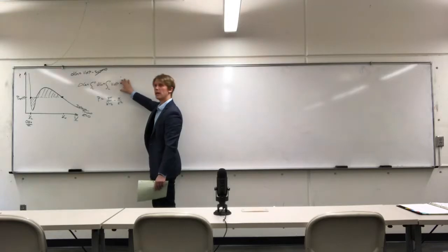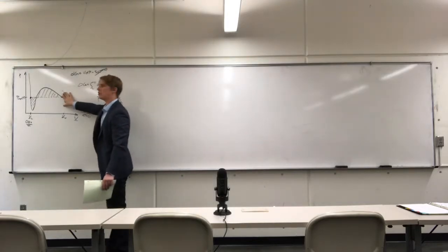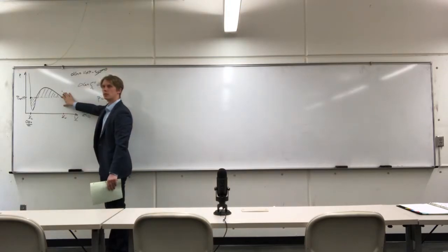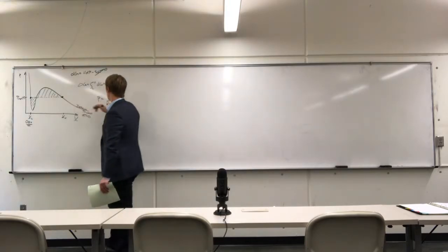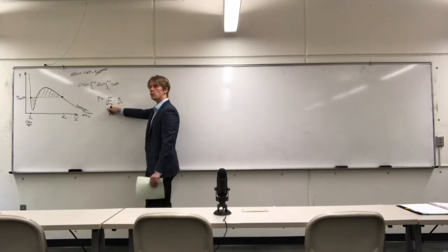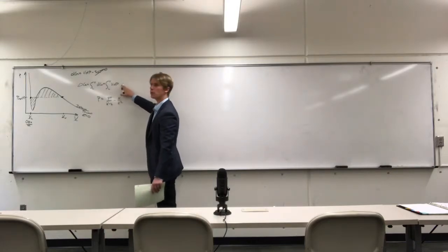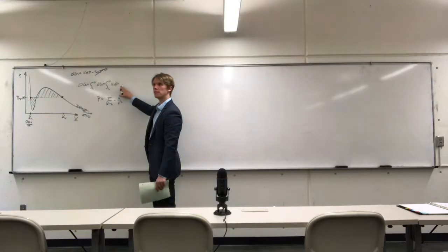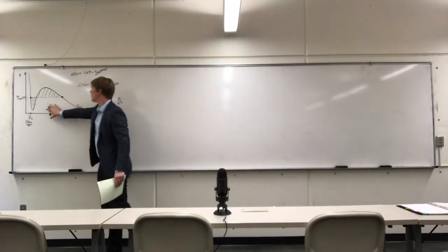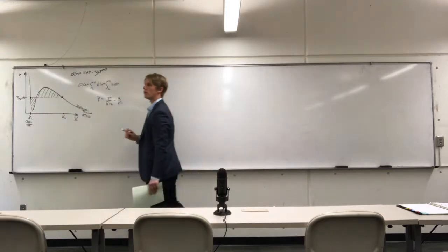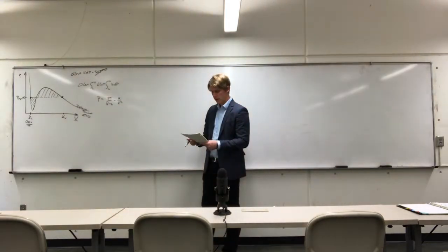If we wanted to apply this numerically, we would more or less have to discretely plot out this function with a particular resolution, solve for the roots of the van der Waals equation of state for every one of our pressure guesses, and repeat those pressure guesses until we find the right pressure that satisfies this relationship here. So it's a relatively cumbersome process. Yes, we can extract phase data from a cubic equation of state, but it does involve a significant amount of work.